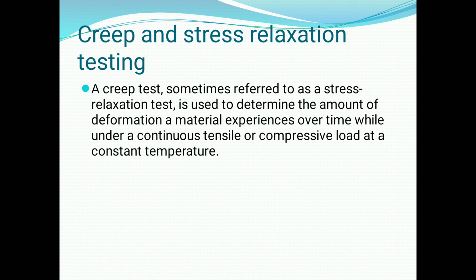And the second test is creep and stress relaxation testing. A creep test, sometimes referred to as a stress relaxation test, is used to determine the amount of deformation a material experiences over time while under a continuous tensile or compressive load at a constant temperature.